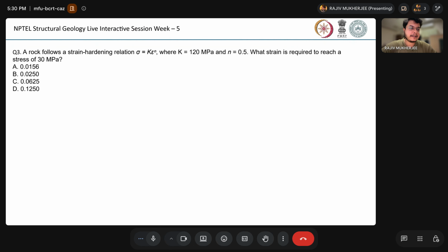We can say that anything but the stress, the yield stress, would be less than 30. What we can say definitely is maximum 30, right? So everything happening here is post yield. So definitely the yield strength of the material is either 30 or even less than that.